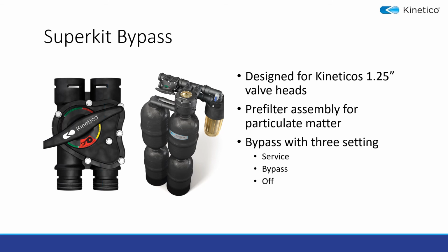And what this allows us to do is have raw water entering on the right cross over into the unit, and treated water exiting on the right but crossing over and exiting into the home on the left. This allows us to do a clean installation without having to adjust any of the piping in the home.